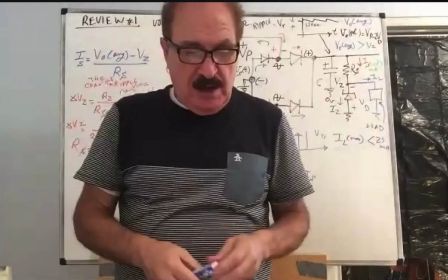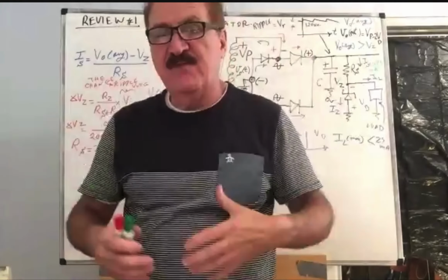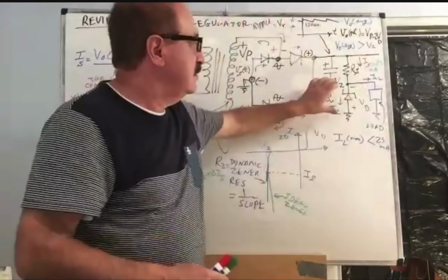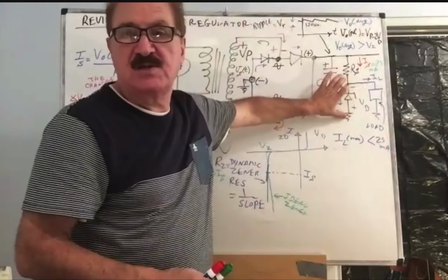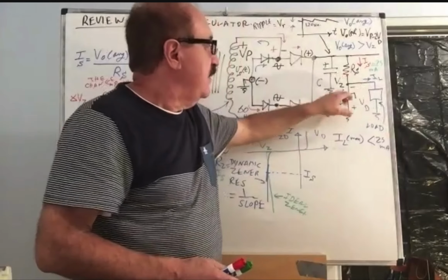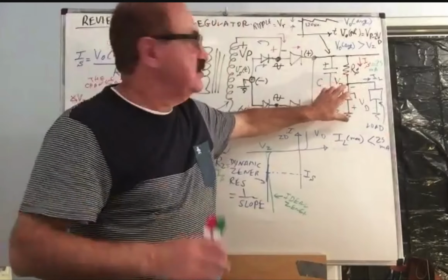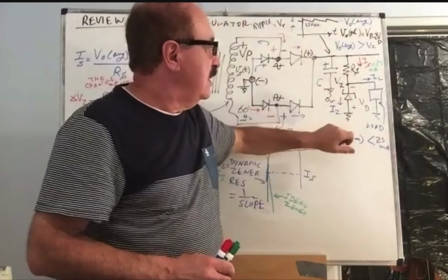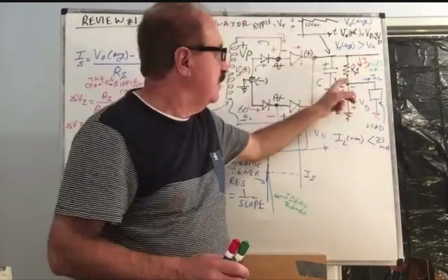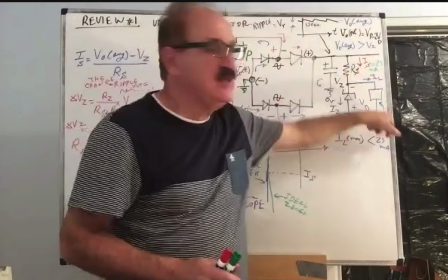I can't arbitrarily take 30 milliamp, 40 milliamp into this load and hope that I will still have the benefit of Zener regulated voltage. The reason is, if the Zener voltage, say, is 5 volts, and you put 50 ohm in here, 5 volt over 50 ohm will already take 100 milliamp.